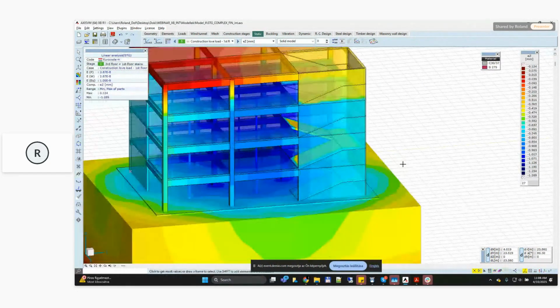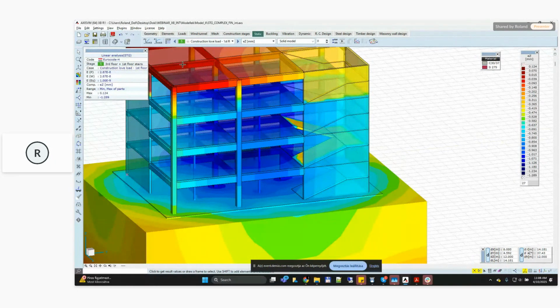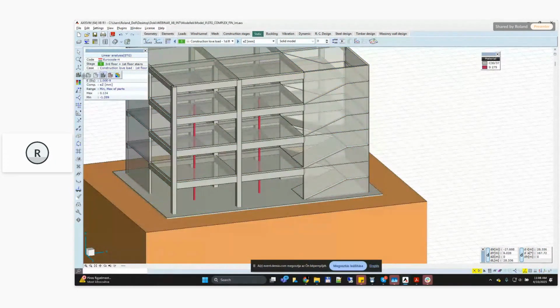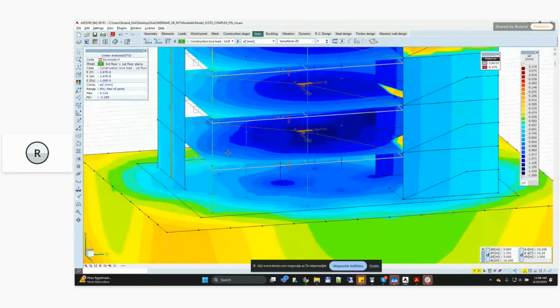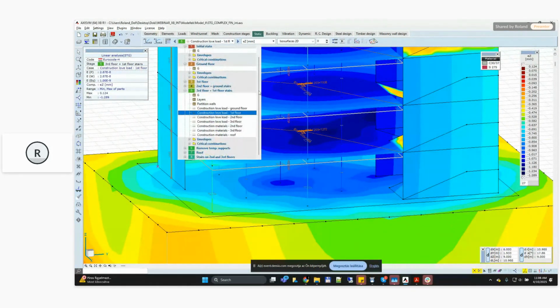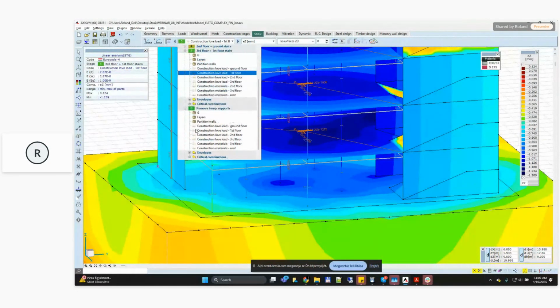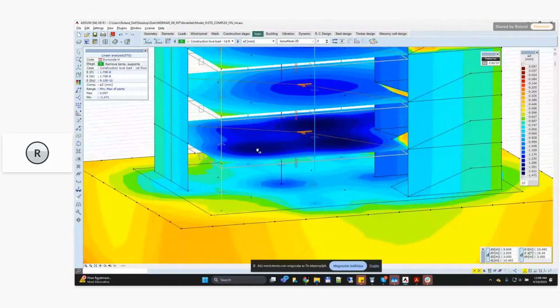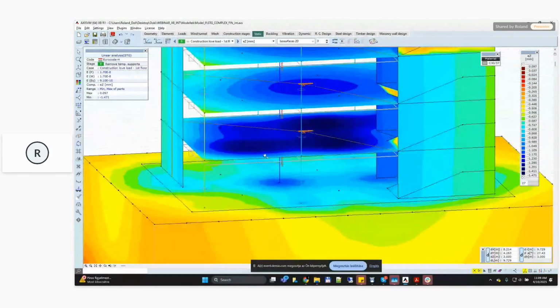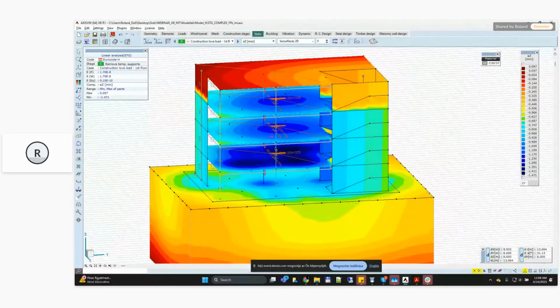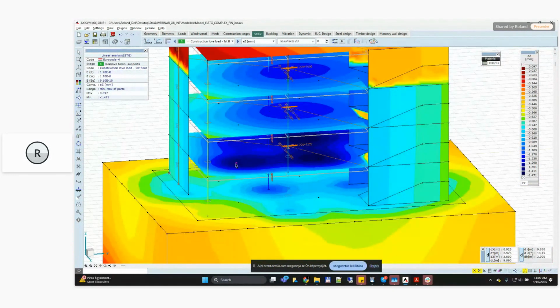Sorry, I wanted to show you the deformations themselves. Let's use this view. Okay, so the fifth stage consists of the temporary supporting structure, and if we move to the next stage, sixth stage, you will see that as they are being removed, the deformations are now according to the changed structural framework, and the maximum deformation values are now in the middle of these slabs.